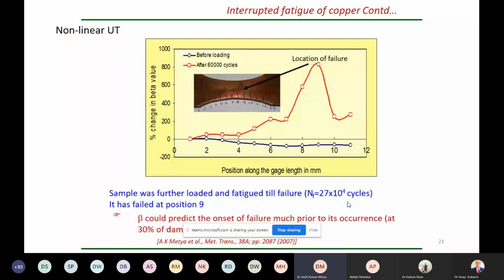And due to this distortion, the ultrasonic wave will give us harmonics that we cannot get from the conventional ultrasonic technique. That's why before crack generation, in that particular position, lots of microstructural things happen, and those things can easily be predicted using this nonlinear ultrasonic technique. So that's why this technique is very, very sensitive to microstructural degradation and deformation in the material.